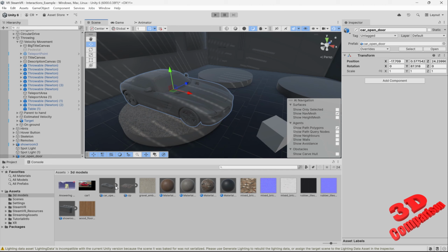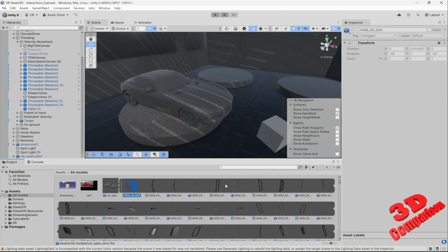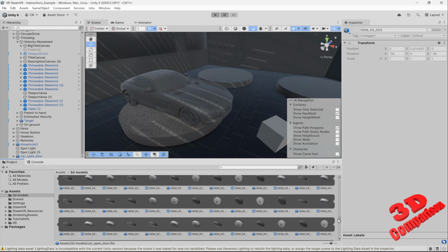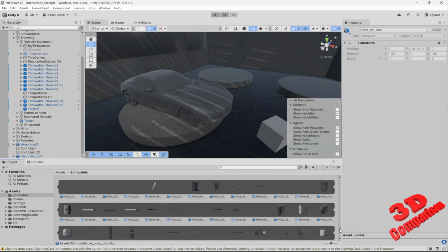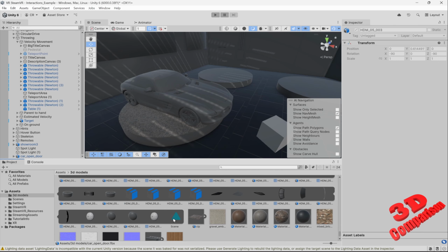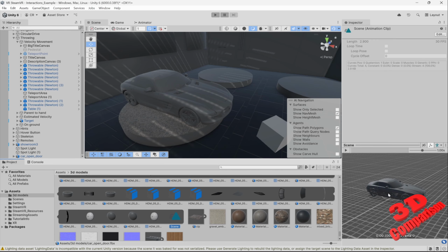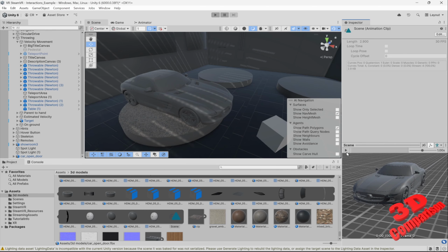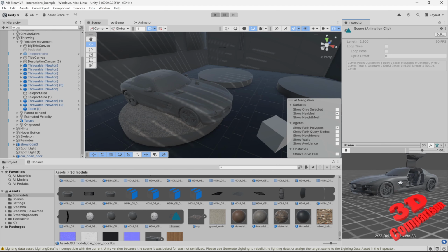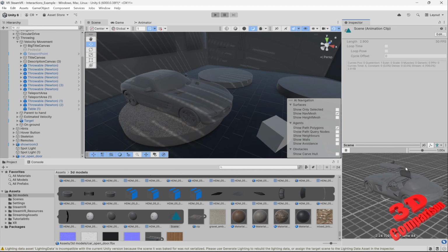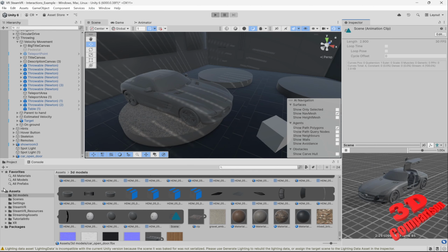And if I will expand that FBX, we're gonna see all of those individual meshes over here at the front. And if I'm gonna scroll down all the way to the back, there are many components. So we need to scroll down, not right all the way to the end. So somewhere over here, the final element will be the animation. In this case, this will be the animation. We see the name, the default one is called scene. If I'm gonna rotate over here within the viewport with a right click, I can also visualize the animation. And we see how that door will open. We only need the door to be open because we can make the close animation by creating a reverse animation of that.